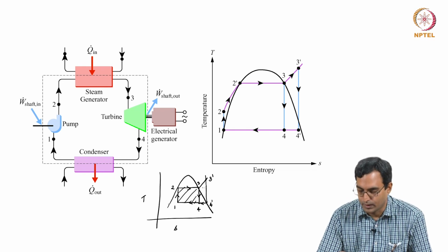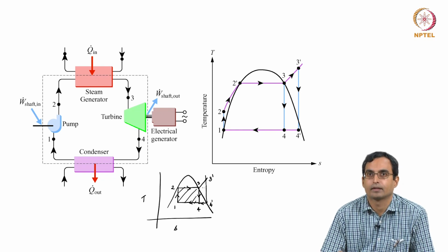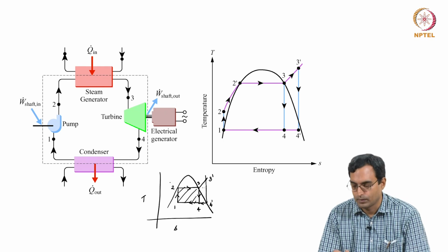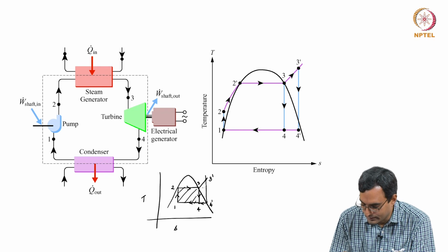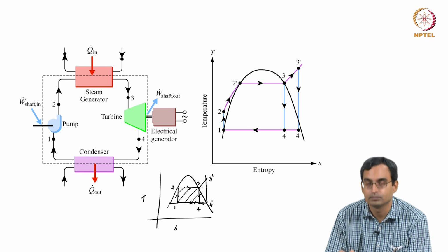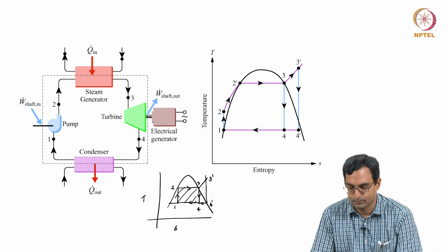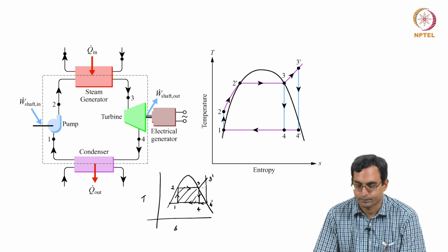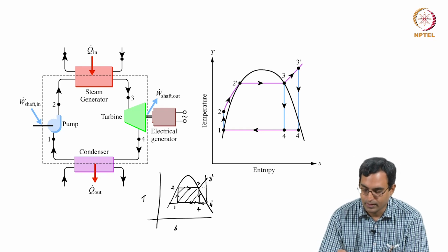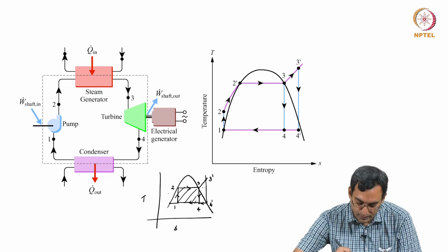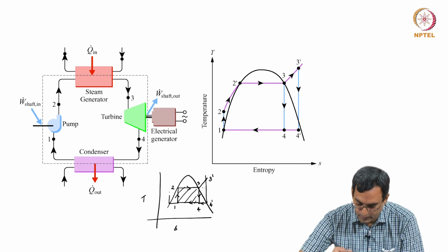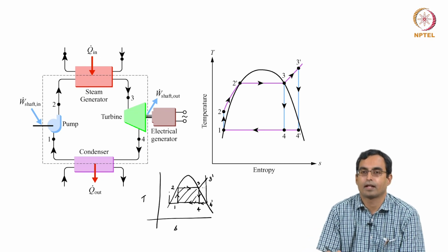We are already very close to the liquid line, because we see that essentially the left hand side of this dome is the liquid line, we are very close to it. So, what seems to be the logical thing is, instead of compressing from this point 1 here, I move to the liquid dome and then I start compressing from a new point which is on the left of the dome. So, I was doing isentropic compression 1 to 2. What I can still do is do isentropic compression from 1. So, I have isentropic compression. I need to compress till I reach the pressure at point 2.